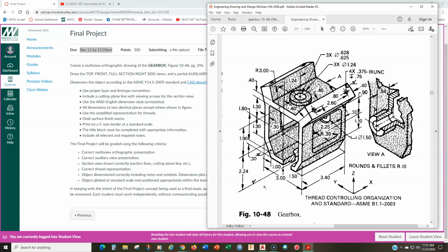The last thing I'll add in here is that all of these edges right here, with the exception of the surfaces that are shown white, well, here, let me explain this. All these corners here, all these edges right here are filleted. They have a 0.10 inch fillet radius, with the exception of these white surfaces, okay? And you can see the white surfaces here.